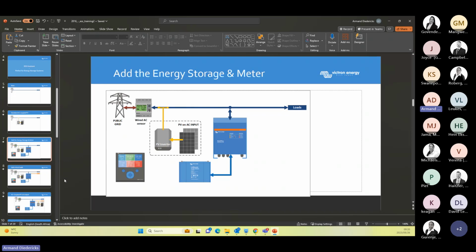So this is a normal backup unit with a PV inverter connected into the input. Worst case scenario, power goes off for 3 days. Your backup system will not have power. You're going to need to have a generator connected. The PV inverter, which is a grid tie inverter, is voltage referenced. As soon as the power drops, your grid tie inverter won't have power and won't produce. Your PV modules won't be able to produce because there's no voltage reference. So it's a good system to reduce the total loads and have backup, but in our current load shedding scenario, it's not ideal.